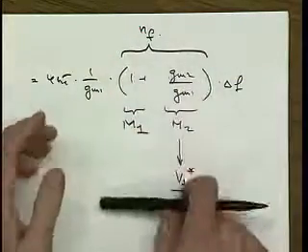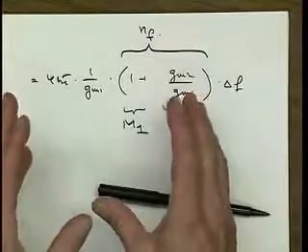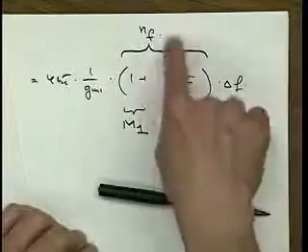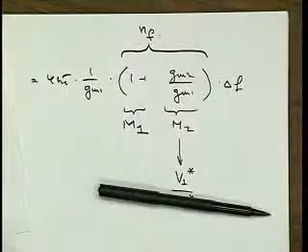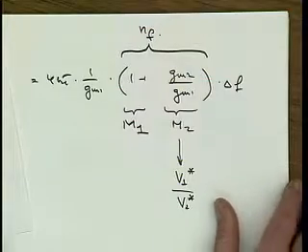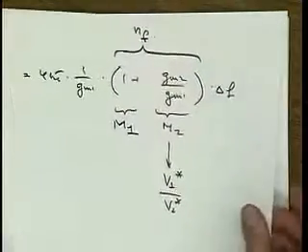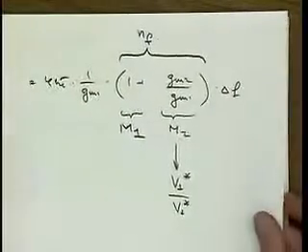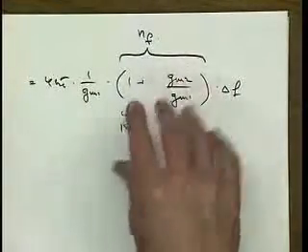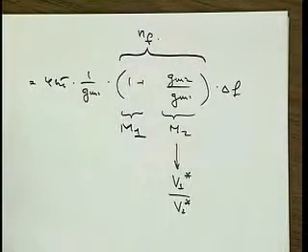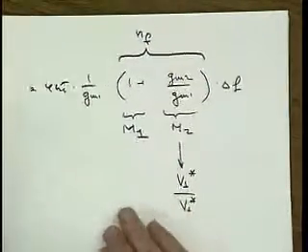When we then later integrate to get the total noise at the output, generally that NF stays, and it still appears in that integral equation. Although we've got to be careful, there are sometimes small modifications to it. Okay, so that's the story about noise, and this trade-off you will see in just about every amplifier. There is such an NF, and one consideration is not to make that NF too big.